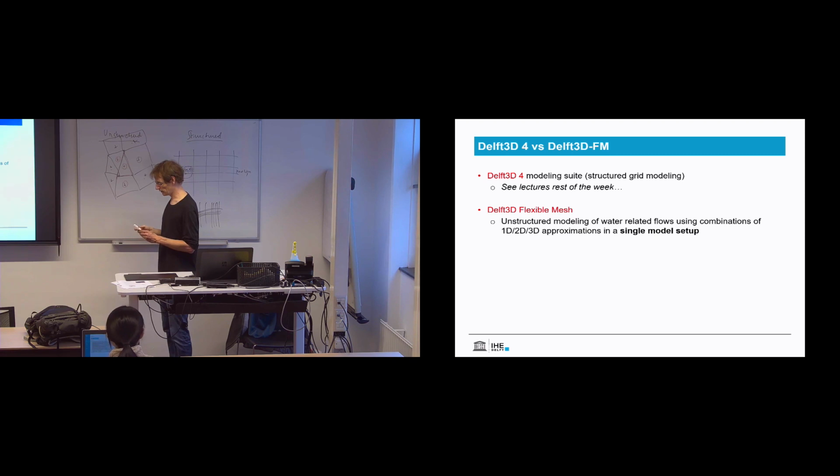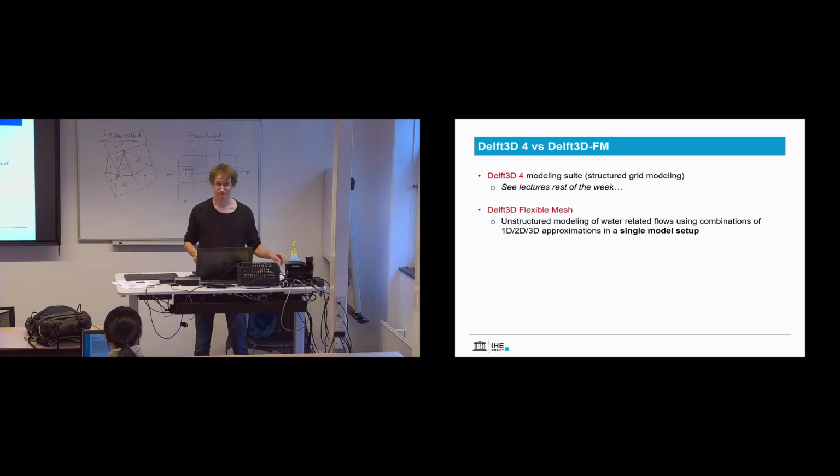And this is really good, because that means you could, for example, split this cell, and this would be a new neighbor, and we have two new cells. Computationally, that doesn't change a thing. It's only a lot more difficult to code. But for the user, it's super easy, because you just make a grid, you draw a polygon, you say refine, and all of a sudden you can double the number of cells or halve the resolution.